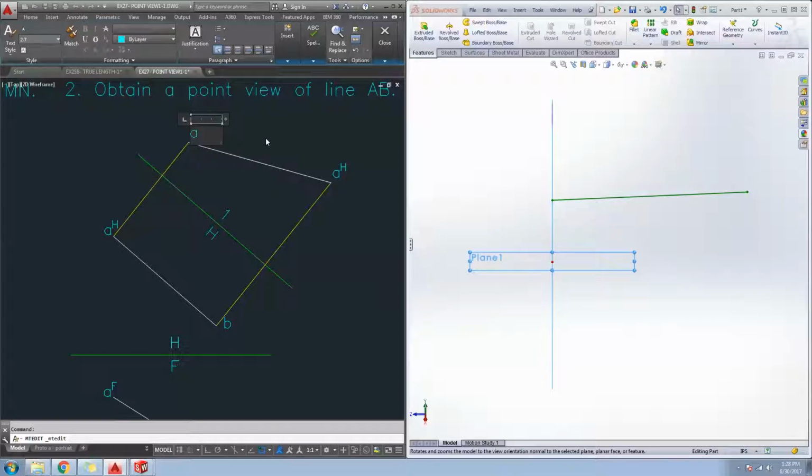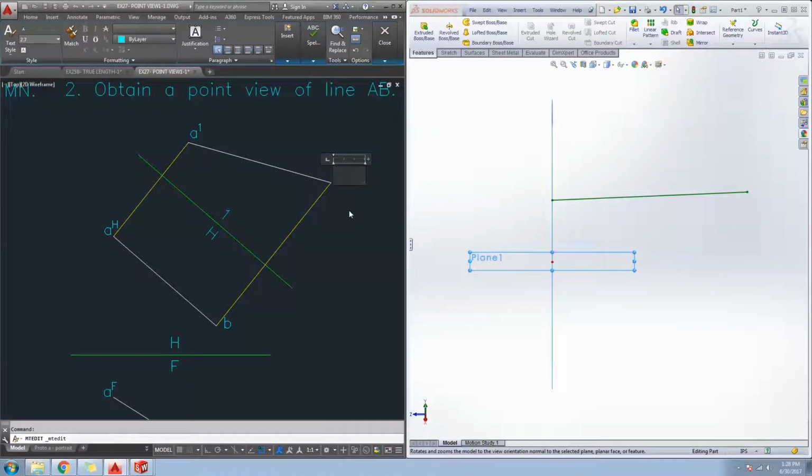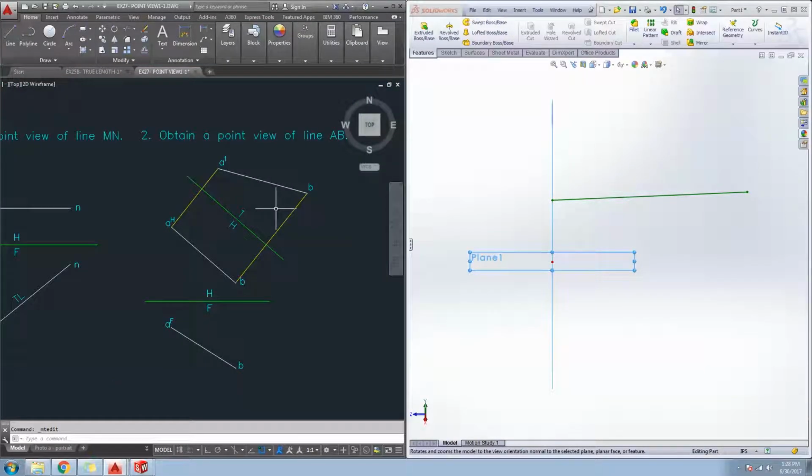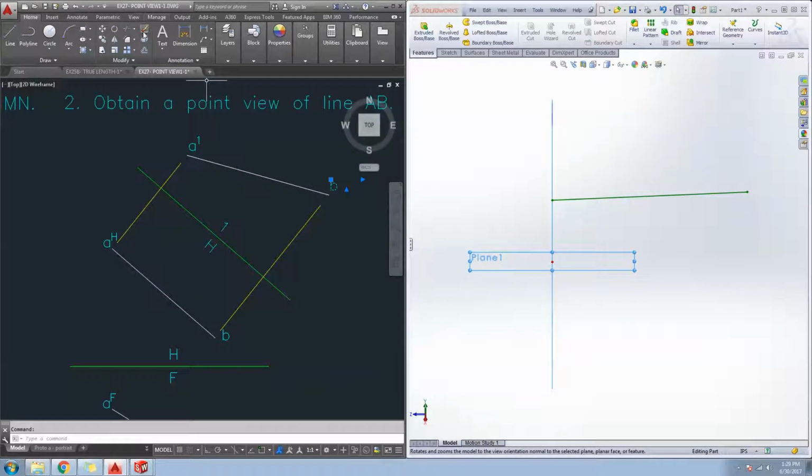And the way I'm going to do that is I'm going to edit my multi-line text box here. I'm going to put a 1 and then a caret. I'm going to highlight it, right click, go to stack, delete both of these, and get Boolean, dy for dynamic, turn off my O snaps, and one last thing to do.